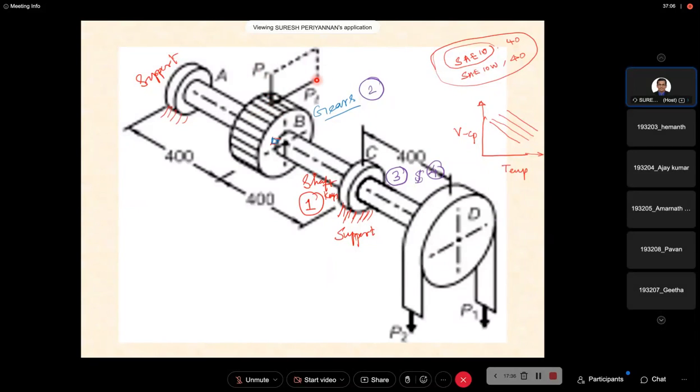The same load will be transmitted through the shaft to the bearings, because the bearing supports the shaft as well as allows its free rotation. Hence, the outer diameter of the shaft is going to be the internal diameter of the ball bearing. Okay, anti-friction bearing. So we have discussed up to this chapter 4.